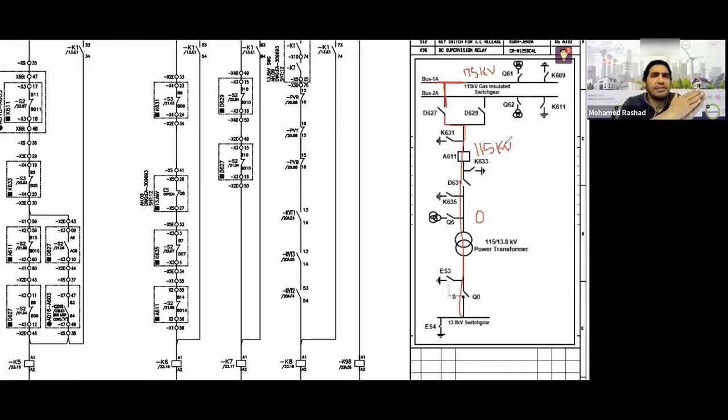The disconnector takes about 3 to 4 seconds to close. During those 3-4 seconds, the two points will definitely drift apart again. With a synchro check, you are checking the voltages until they match, then you close the breaker. The breaker closes in milliseconds, so it catches the two points together, whereas the disconnector takes 3 seconds, during which the two points might drift apart again. Consequently, at the moment of closing, you might experience a spark or arc.